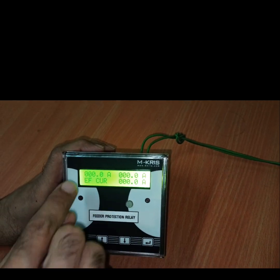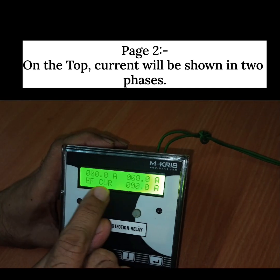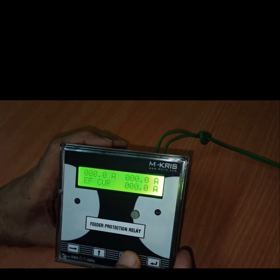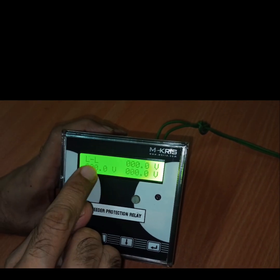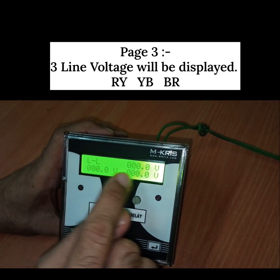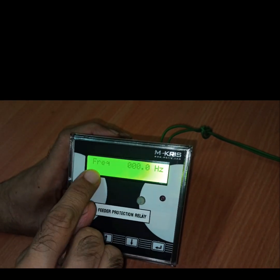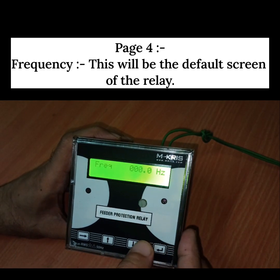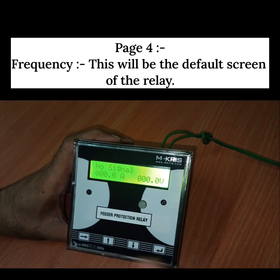When we go to the second page, we will see the current in 2 phases which are connected, and in the bottom line, earth fault current will be displayed. In the next screen, we will be able to see the 3 line voltages RY, YB and BR. And the last page shows frequency which is there in the system, and this will be the default screen.